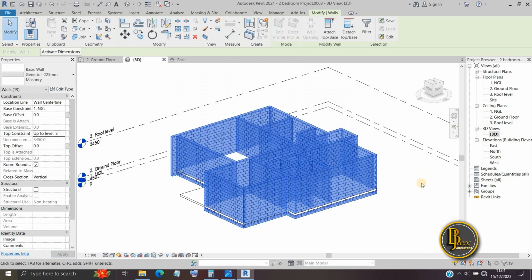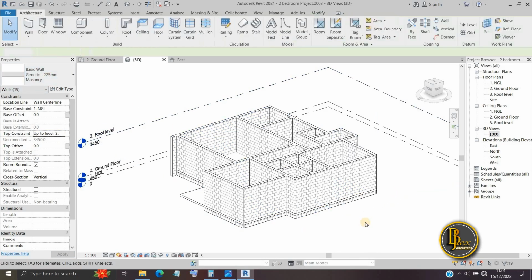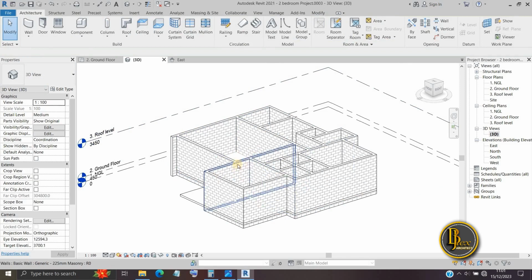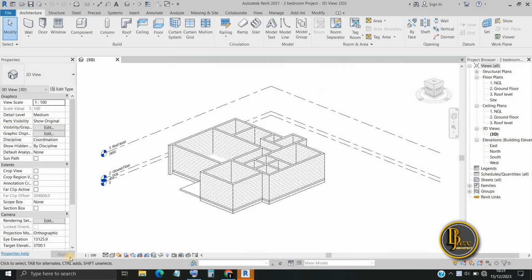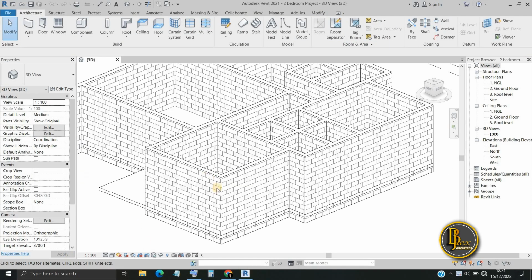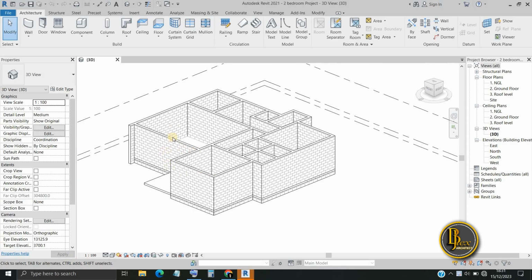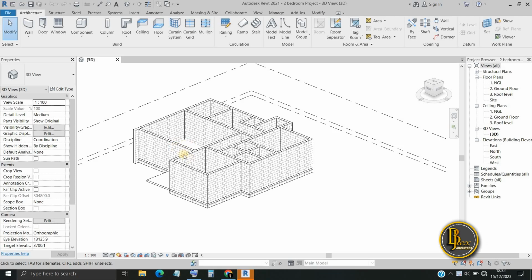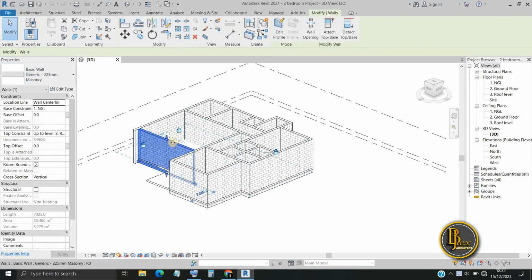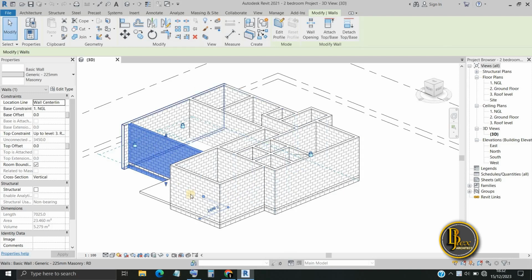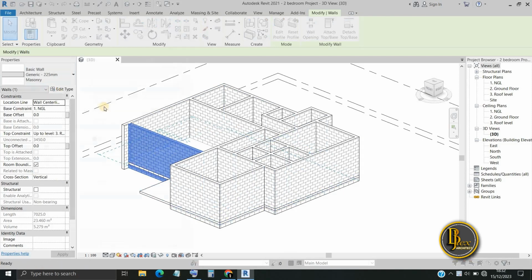Now it's looking okay. You understand why this thing is in brick, because we are using Masonry brick wall, but we can change the structure of this brick to be plain, to be black, or whatever you want it to be. So at the moment, this Masonry block has some kind of pattern to it. So let's remove that pattern. All you need to do is click on one of these. When you click on it, it will give you the structure of this particular block, and this block is the same as every other block here. So just edit just one.